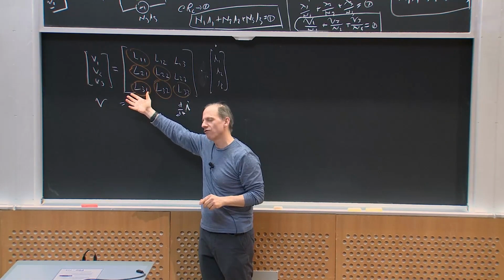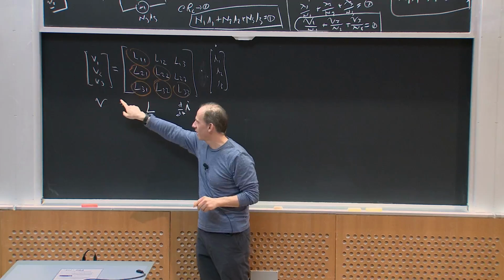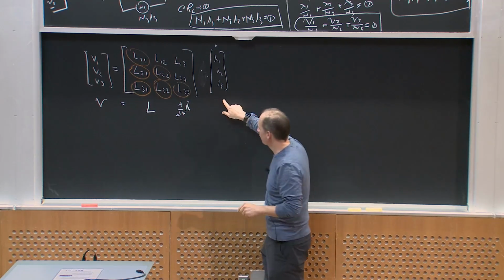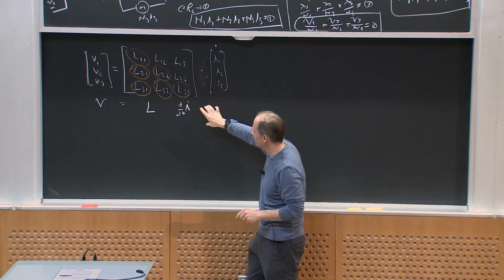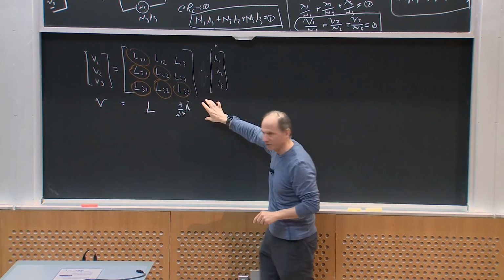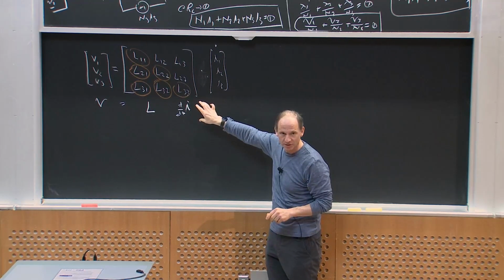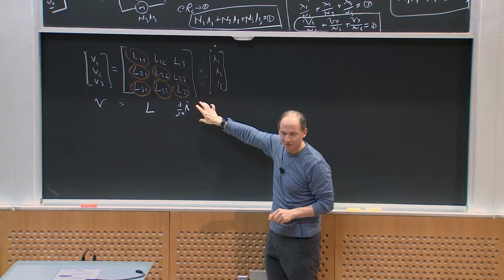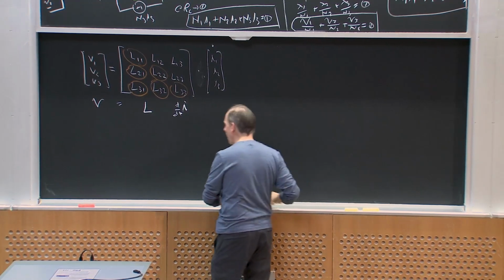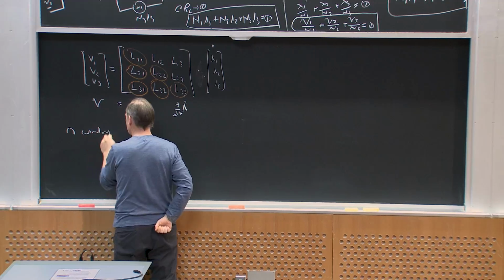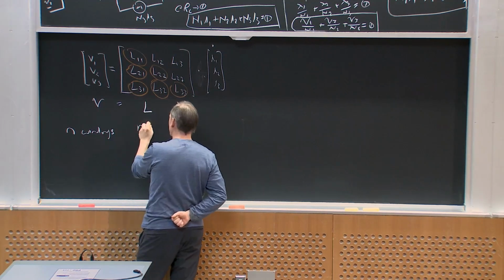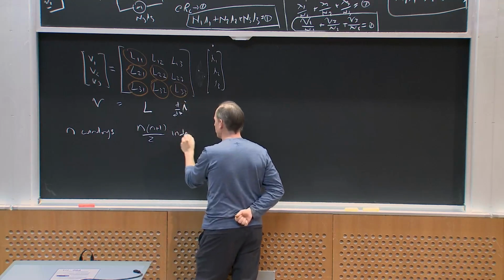What would happen if I had a 4-winding transformer in the general case? Well, I'd add a V4 and an I4, and then I'd basically add one more bottom row of independent parameters, 4 parameters, and I'd have 10. Okay? So it turns out that an n-winding transformer ends up with n times n plus 1 over 2 independent parameters.